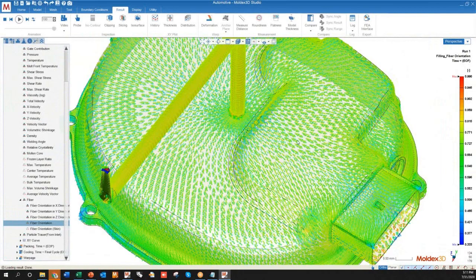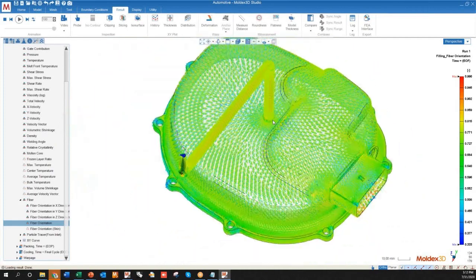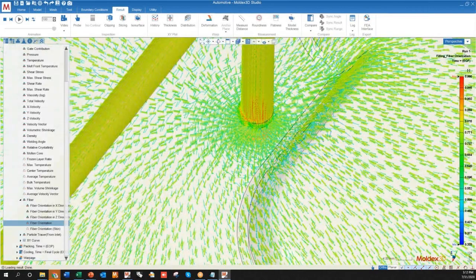So really, what we ultimately want is somewhere right in the middle here. We want the primary direction to be controlled so that we get a good modulus distribution, but we also want some amount of orientation in the opposite direction so that the modulus doesn't decrease more than what we would want. We want to be able to control all three directions if at all possible, with a particular focus on one of them.